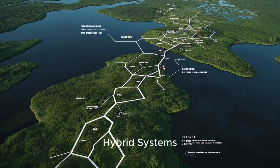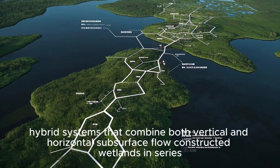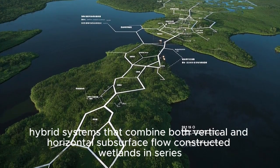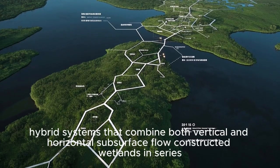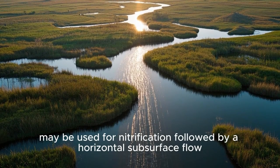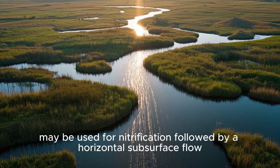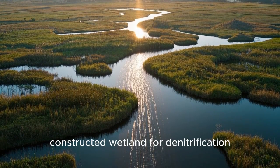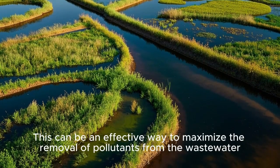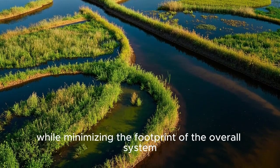Hybrid systems. Some aquaculture operations may use hybrid systems that combine both vertical and horizontal subsurface flow constructed wetlands in series. For example, a vertical flow constructed wetland may be used for nitrification, followed by a horizontal subsurface flow constructed wetland for denitrification. This can be an effective way to maximize the removal of pollutants from the wastewater while minimizing the footprint of the overall system.